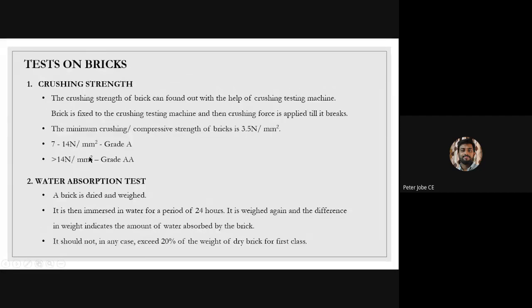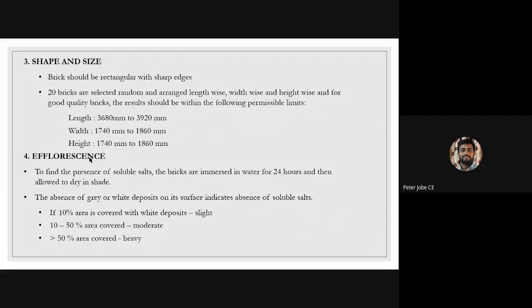So we have gone through 3 different tests. First is the crushing strength, second is the water absorption test, and third is the size and shape test. Then we need to find out the efflorescence test too. To find the presence of soluble salts, the bricks will be immersed in water for 24 hours, and then allowed to dry in shade.